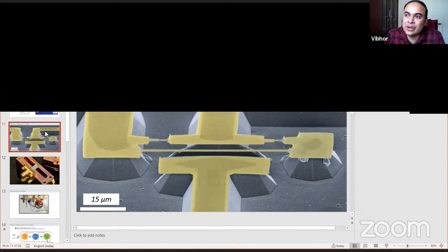From the TLS point of view, what we are doing is removing most of the dielectric. I did not get into too many fabrication details, but this qubit is patterned on top of silicon nitride, which is a well-known material with lots of TLSs. So we were not expecting very high T1 or T2 for this qubit because it's partly patterned on silicon nitride. Although when we do fabrication we try to remove silicon nitride, the one below the aluminum you can't get rid of.